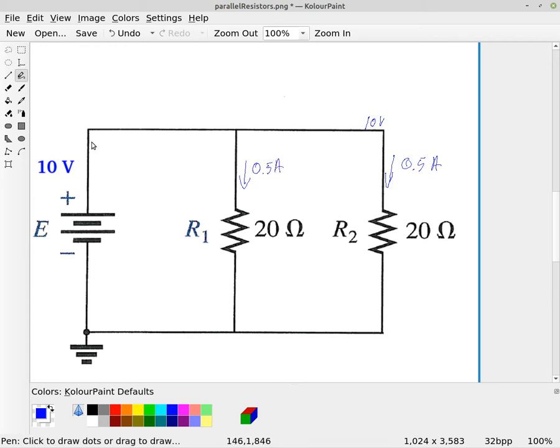So what does that mean? It means now that this power supply has to provide enough current to come over here and let half of that current go down this way and the other half go down this way. So if we were to put a current meter in series right here at the power supply, we would be reading 1 amp. So again, if we're going to put that in Blackboard with 3 significant digits, it would be 1.00 amps. All right, which means also that if we were supposed to put the current meter down here, it would be reading 1 amp.